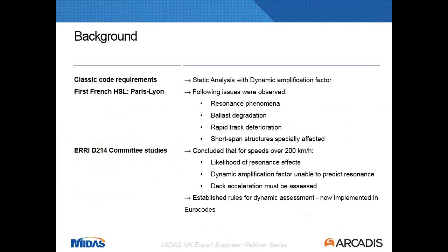And when this line was put in service back in the 80s, some problems were observed in some of the bridges. Some bridges exhibit some resonance phenomena, and the ones that did, it was observed that the ballast degraded very, very quickly. There was a rapid track deterioration, and also short span structures were the ones with more severe effects. In view of that, in a joint effort in Europe, a committee was constituted to study this problem.